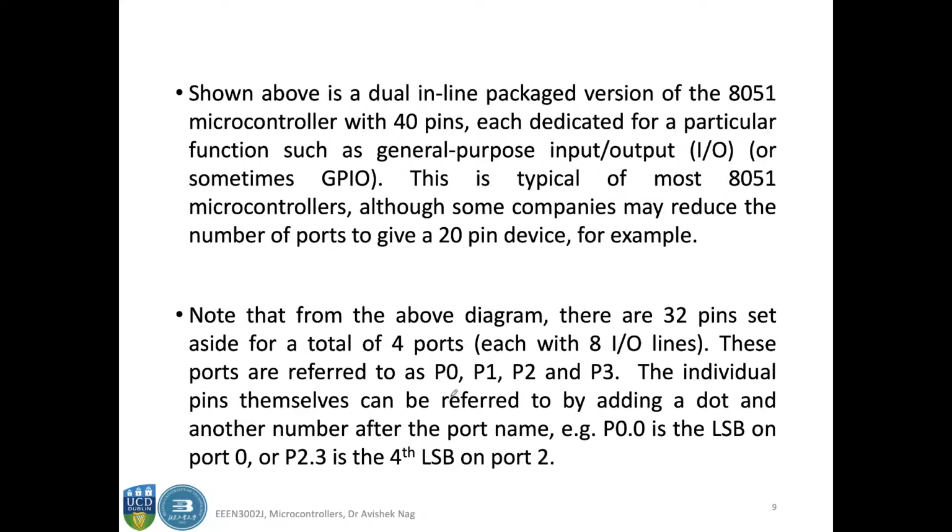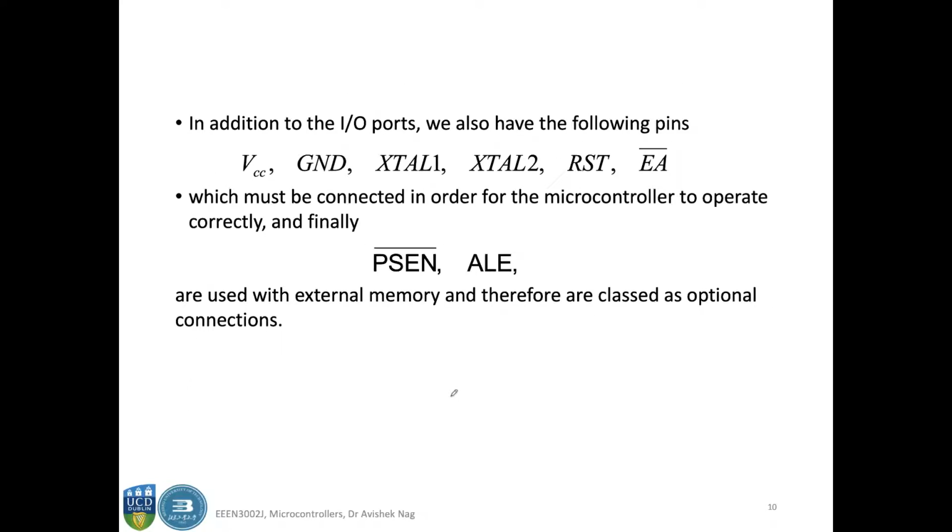So this slide actually summarizes what I just said about the pin structures. So apart from the 4 ports and the 32 pins associated with those 4 ports, you have VCC, ground, crystal 1, crystal 2, reset, EA, PSEN, and ALE. So let's look into the functions of these.